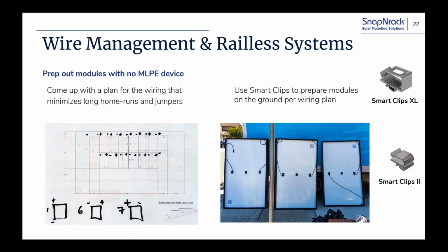So this is an example of managing the PV wire with a standard string kind of system. Here we have some sort of half cell module with the J boxes in the middle. A simple way to do this, while you're getting used to it the first couple times, is you can just simply draw it out on the plans. And that's what I had these guys do.